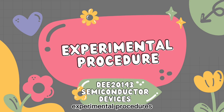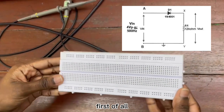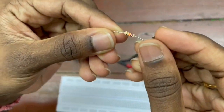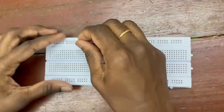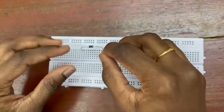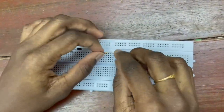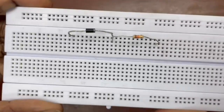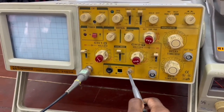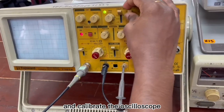Experimental procedures. Half-wave rectifier. First of all, construct the circuit as shown in the figure above. Then connect the probes to the oscilloscope and calibrate the oscilloscope.